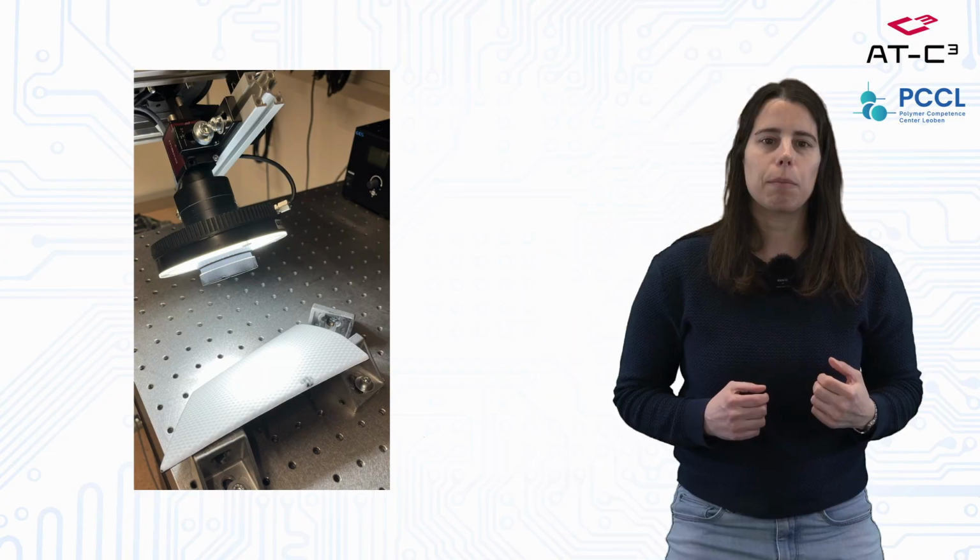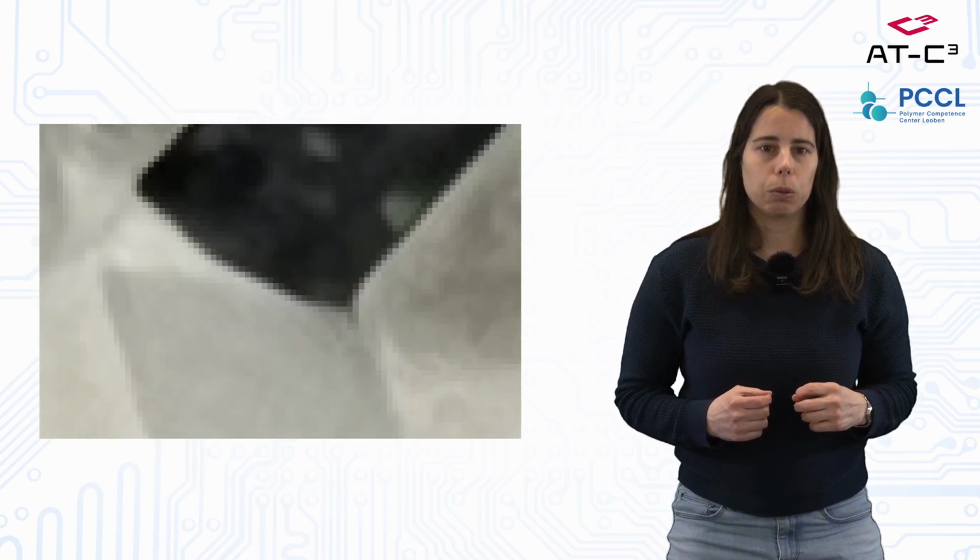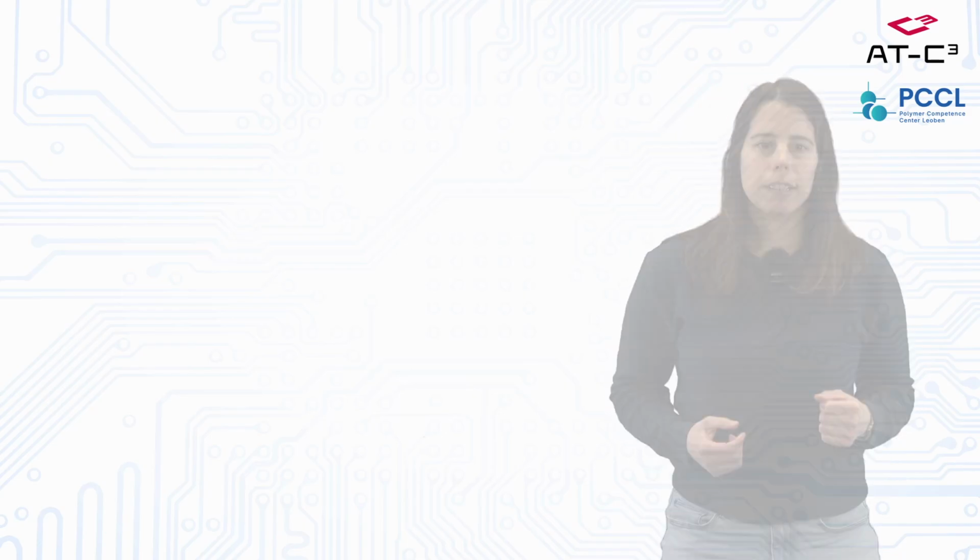Automatic optical surface inspection was developed to enable the effective testing of high product volumes. At its core, it works like this. A camera captures images of the product and algorithms analyze these images based on defined rules. Each image consists of many individual pixels with different brightness and color values. These are evaluated using classical image processing to detect defects and evaluate the product. Based on this, let's look at how classical image processing works.